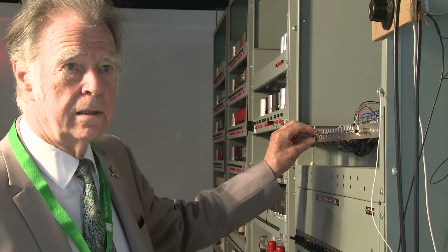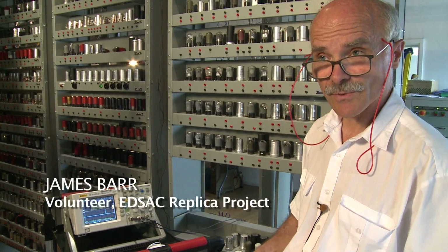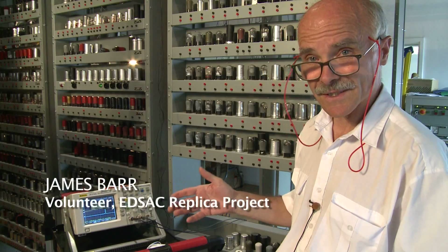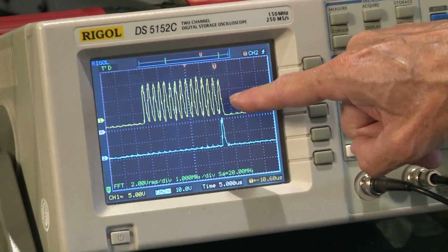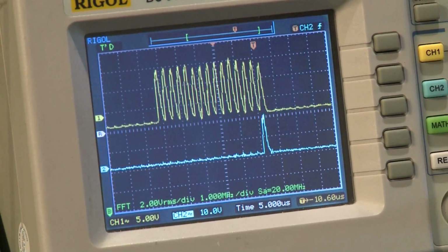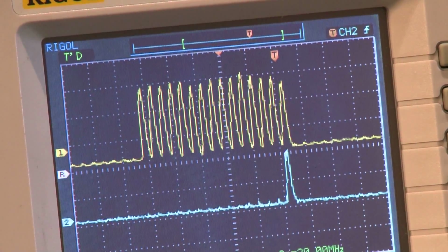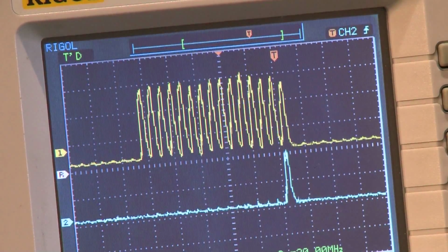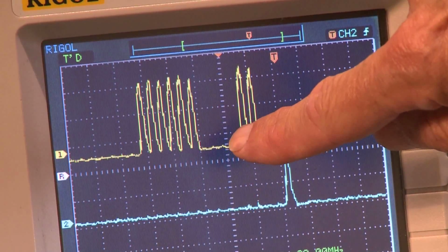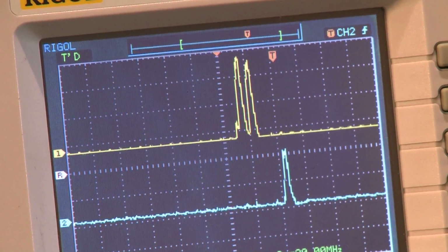John is operating the engineer's test switches at the moment. This is a means by which we can inject specific orders into the machine for repetitive execution. And you can see the whole word here that's stored in the order register. The rightmost 5 bits are those bits which are used to decode the order. When John sets one of the switches down, you'll see a specific bit disappear. So he's able to control individual bits in the order tank by that means.